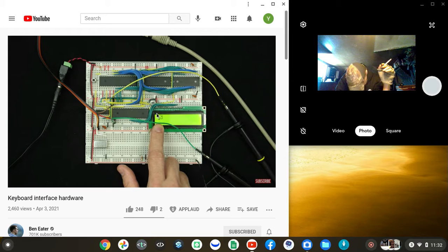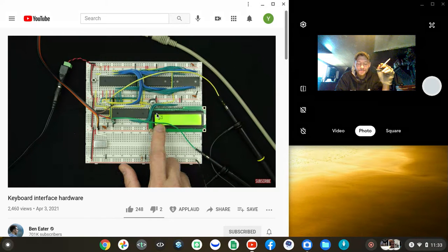And that's because when I press the key, we get 11 bits to indicate that the key's down. And then when I release the key, we get 11 bits to say that we're getting a scan code for the key that's being released. So that's another 11 plus 11, and that gets us to 33 bits.